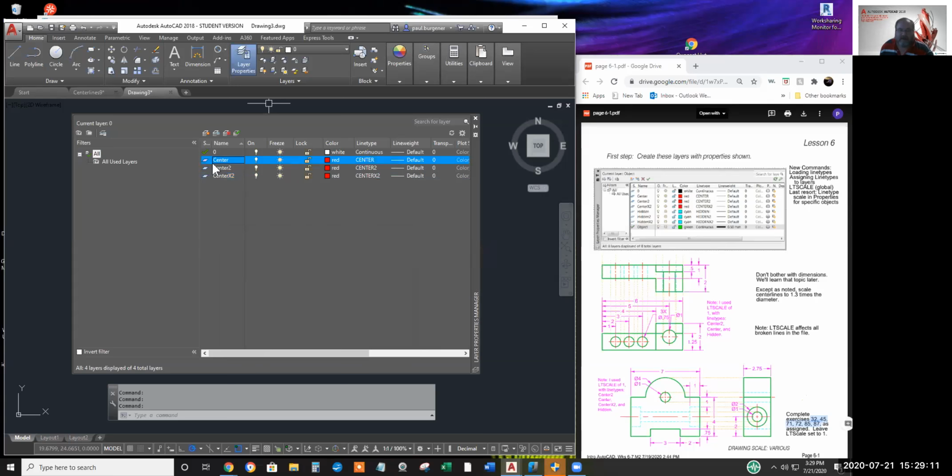But again, the line type that's got just a simple name with no 2 and no X2 after it, that line type is kind of the average length of line space, long line space, short line space, long line space, Morse code on and on. Center X2 is super long and center 2 is shorter than center.